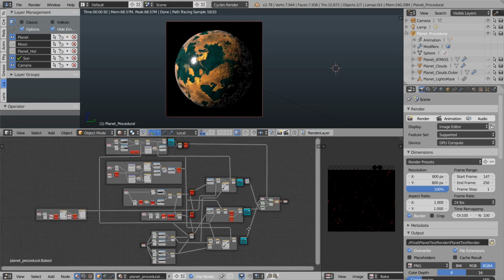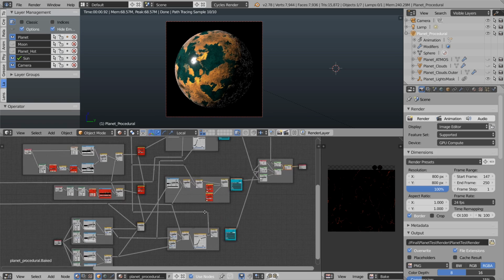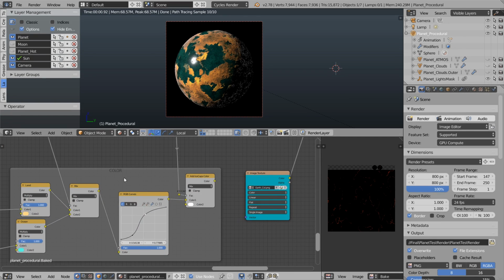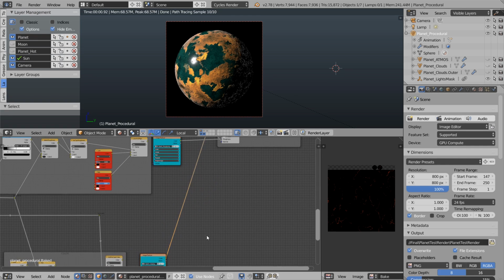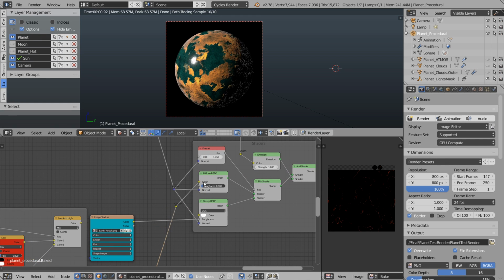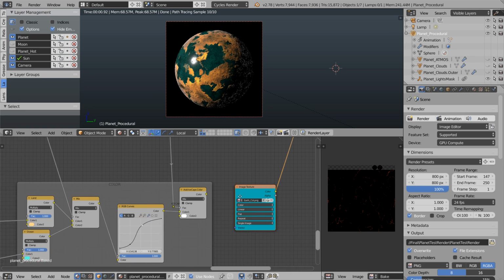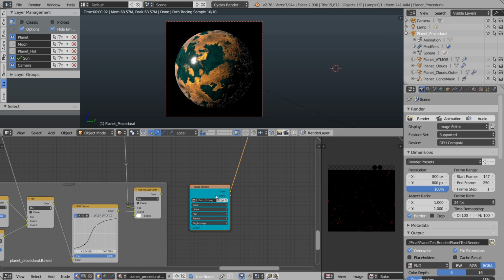So let's zoom into one of those baked texture nodes. I'll zoom into this one down here, which is sat in front of this color frame. This image texture node is just coming into the diffuse shader's color. So what we can do is just come back over here. And if we've got the Node Wrangler add-on enabled, which we should have, let's go Control Shift and click on this image texture node. And we can see the results of just this one texture node plugged into an emission shader, which makes it nice and fast to visualize in the viewport for us.